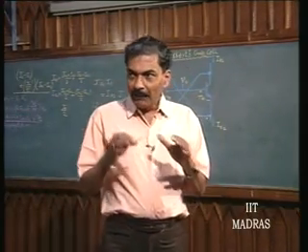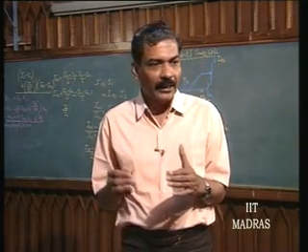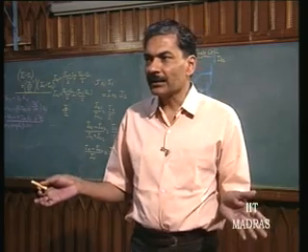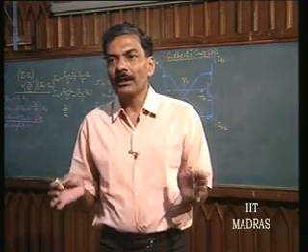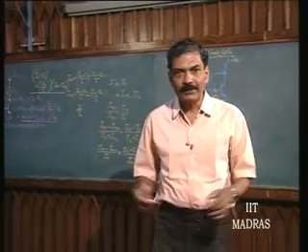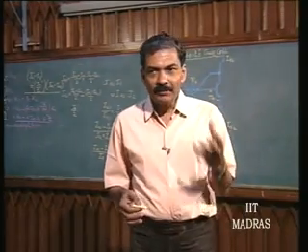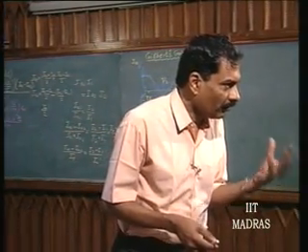If you don't adopt negative feedback, then all the problems associated with negative feedback, like need for frequency compensation, all these things are not existing, and therefore this concept can be adopted for designing what are called as wideband amplifiers or video amplifiers.